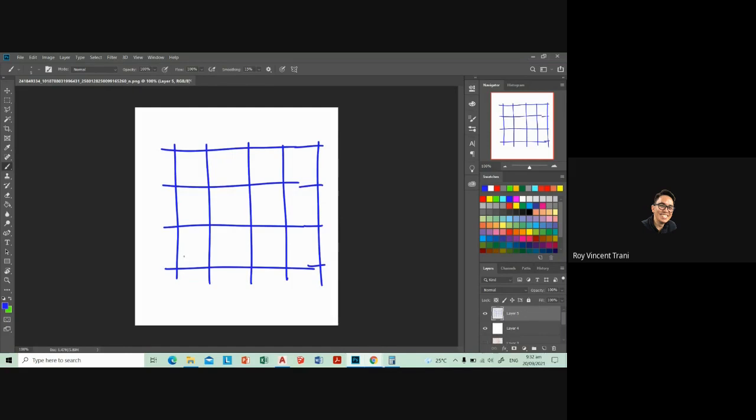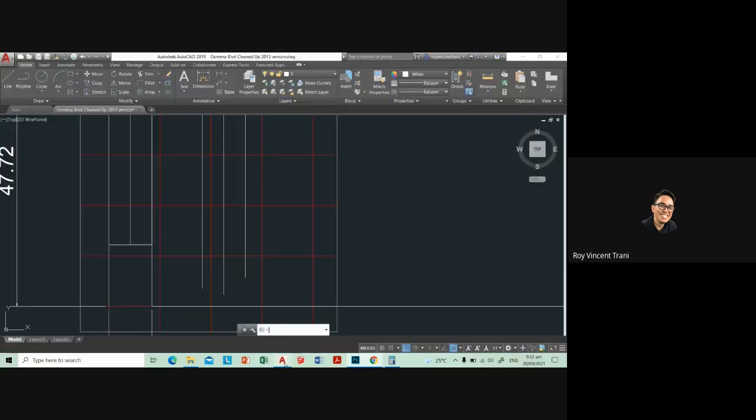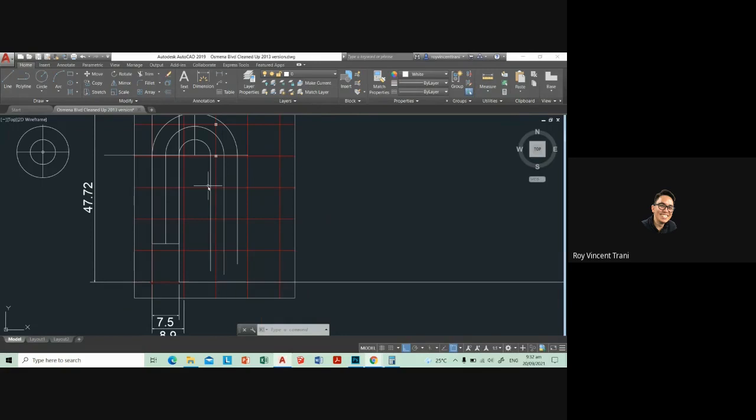You need to have your 25-meter run somewhere over here. And then maybe they can turn 90 degrees somewhere. Although I really advise that, maybe better, not the column, the ramp would be somewhere here. So you can make the turn here, which is what we're doing in the AutoCAD version over here.